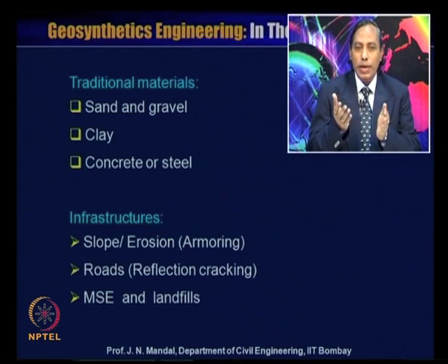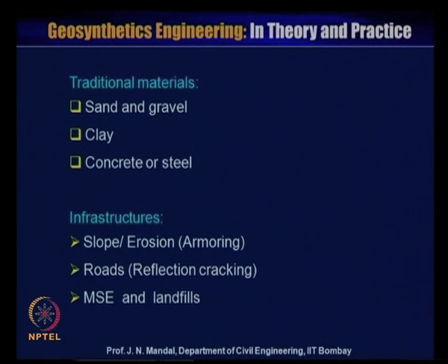I am just showing here some of the infrastructure and how the geosynthetics can help to reduce the energy, how you can save the money, how you can save the time, how you can make use of it in a sustainable manner. So we are focusing here only on infrastructure like slope and erosion, hardening, road, reflection cracking and mechanically stabilized earth wall, that is MSE, and the landfill.